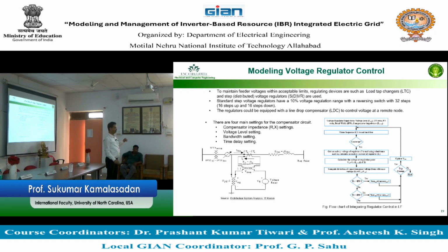Normally, the line drop compensation will look at a point on the distribution network somewhere 2/3 from the substation. 2/3, 1/3 is a thing. So you go to the 2/3 point and take that load connection or load drop from there.